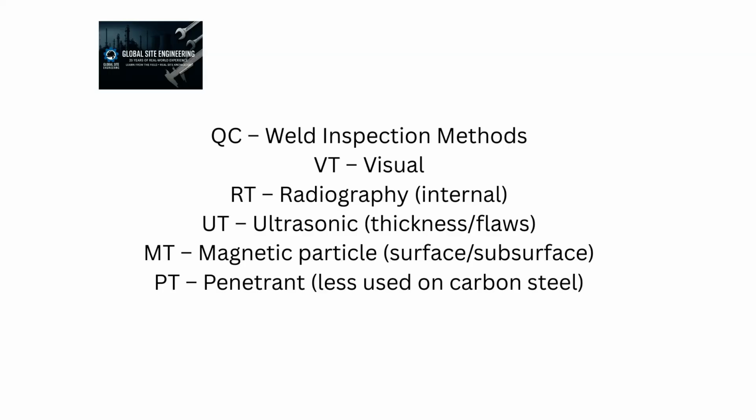QC weld inspection. Quality control is a must. For carbon steel welds, we use visual testing for surface flaws, radiography for internal defects, ultrasonic testing for volumetric flaws, magnetic particle testing for surface and subsurface cracks. Penetrant testing is less common here, mostly used for non-ferrous materials.